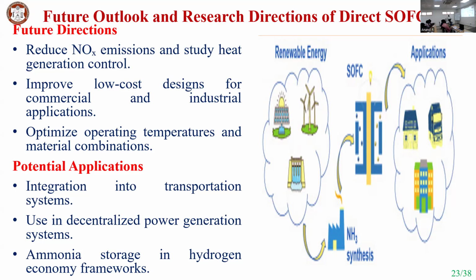There are also challenges. Ammonia is highly corrosive in nature and also toxic. Naturally, when using ammonia in an engine, you are already introducing 79% nitrogen from the air. Along with that, the nitrogen dissociates further during burning and comes out. It also leads to more NOx emission compared to burning diesel fuel in a diesel engine or petrol fuel in a petrol engine. So we need to take care of that.